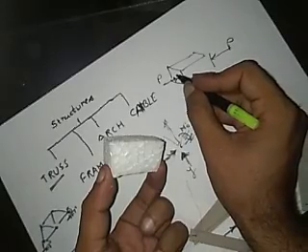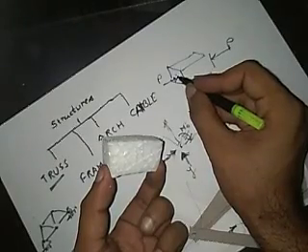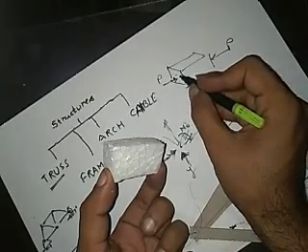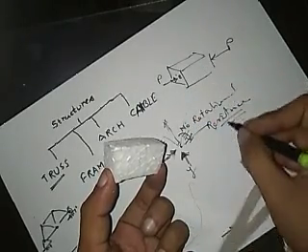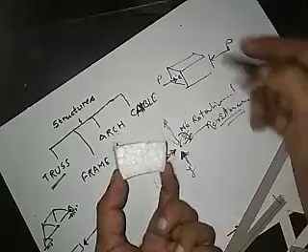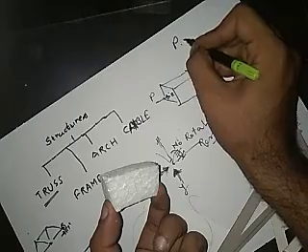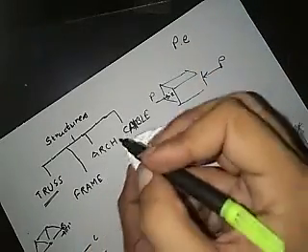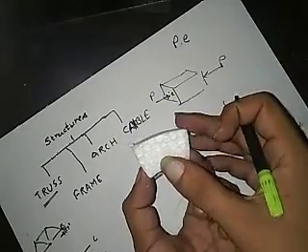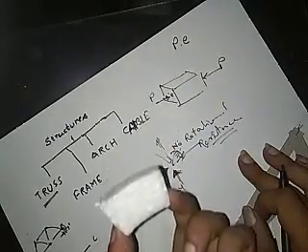If it is acting somewhere below or above the centroid axis, the centroid of that cross section, say at some eccentricity E, then there will be a moment whose magnitude will be equal to P times E. Okay, so what kind of moment is this? This is a hogging type moment. I'm applying a compressive force near the bottom layer, not at the centroid.